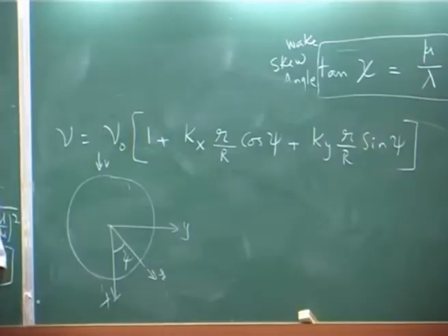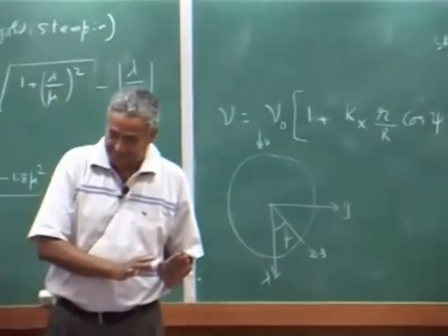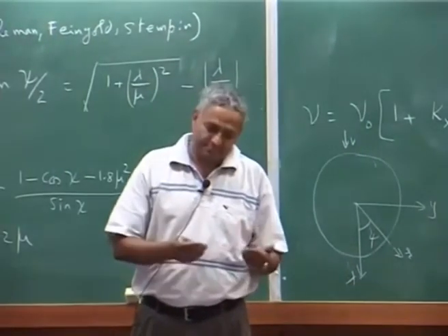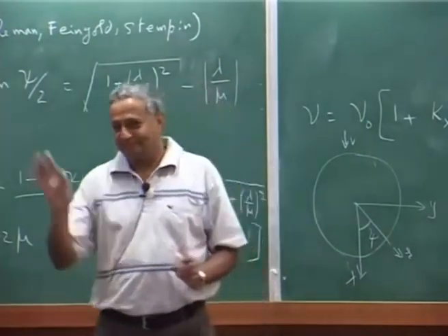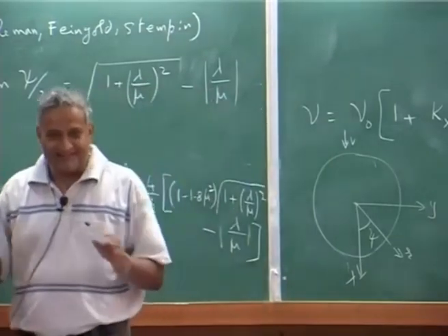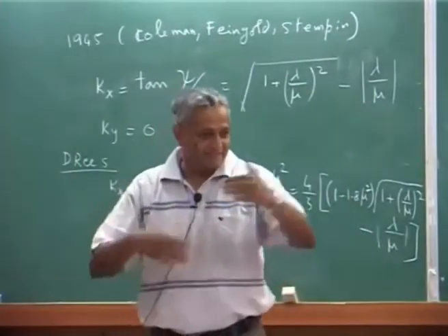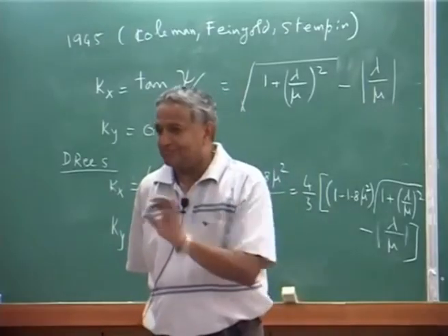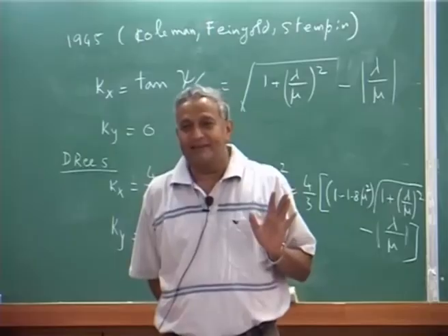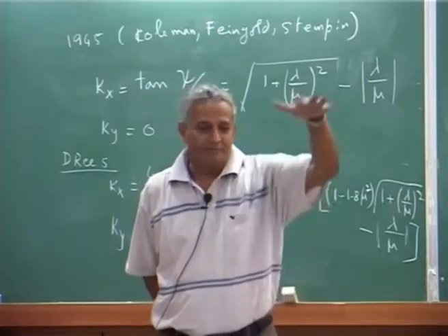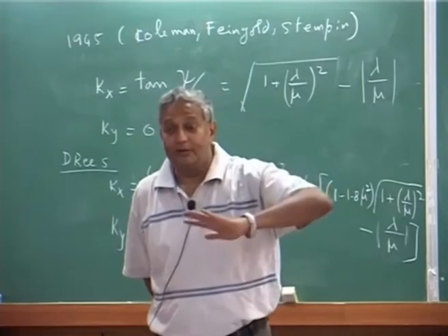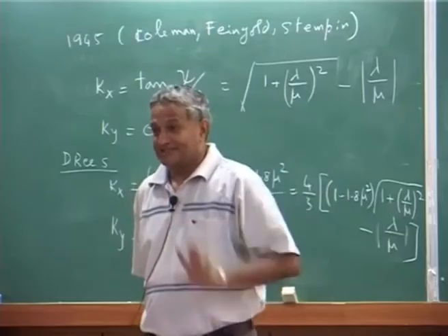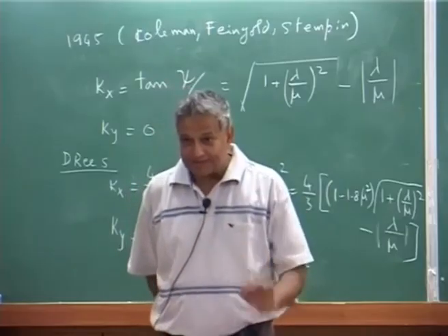Okay. Is it clear? Which is a gross assumption, but if you want to get some closed form results in a reasonable length of mathematics, basically algebra, then make an assumption that my inflow is uniform over the whole disk, even though it is not correct.